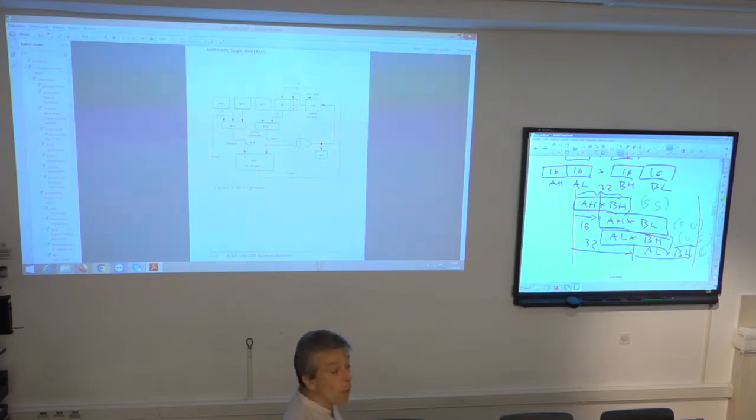So you get only one bit at a time of the quotient. So you have actually this instruction, DIVQ, and you repeat this instruction 15 times, and the first one is for the sign computation, and then you repeat this one that does the division 15 times, and you get the 16-bit result of the division.